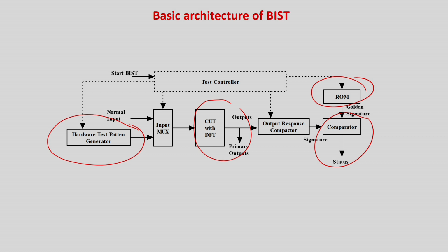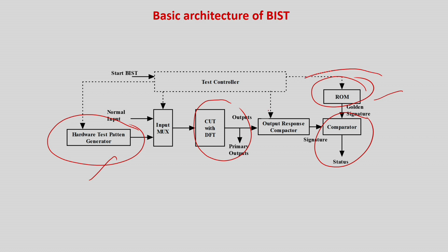If you are going to do it, the size of the test pattern generator and the size of the RAM where the expected responses are stored, and the comparator will be so large that it will be much larger than the chip itself. So it will be like killing a mosquito with a cannon. You are not allowed to do that. You will be able to do a test provided that this hardware pattern generator and this whole output response analyzer circuit are very small compared to the chip. So that is the challenge.